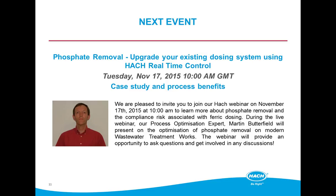The danger you would have is if you had an extremely high load that hit and you had a DO, just say you had a minimum DO set point of 0.4 or 0.3, something like that, then you might find that it automatically overwhelms what the aeration system is able to provide for a short period of time.